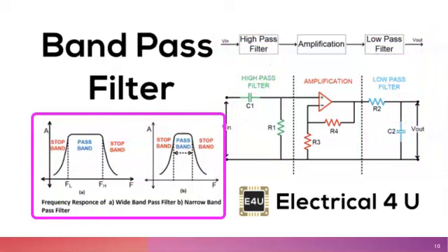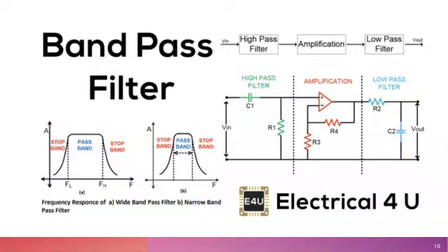The huge gain of the op-amp can lead to instability if steps are not taken to ensure that the op-amp and its circuit remain stable even with negative feedback applied. In its basic terms, a small capacitor is added to the internal elements of the op-amp, and this has the effect of reducing the tendency to oscillate, but it also reduces the open loop bandwidth. But this aspect is not covered in this video.